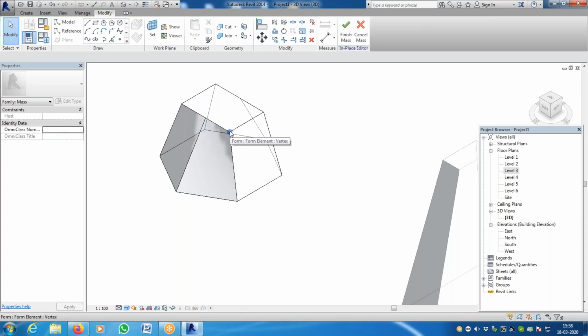Why do we have split element? Split element is to create a proper massing. It's all right if you don't have split element. Also, it creates a kind of mass. There is no rule that mass has to be like this or like that. However, if you want to create a perfect geometrical mass, a symmetrical mass or something like that, at that point you might have to use the split element. Is that clear for you?